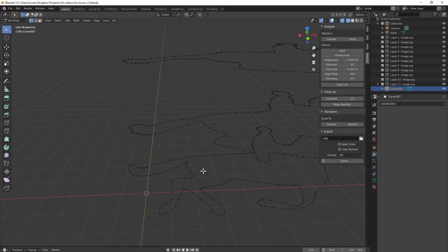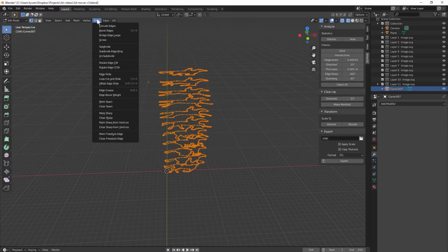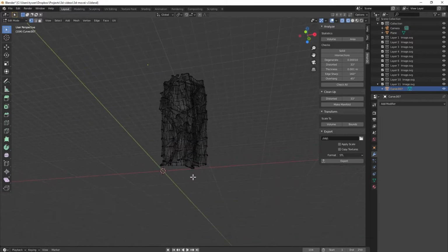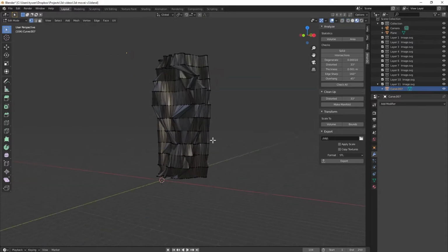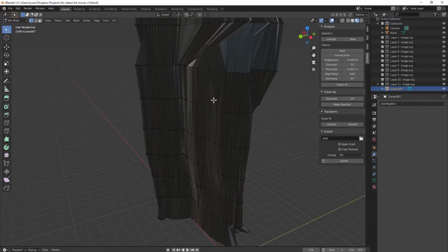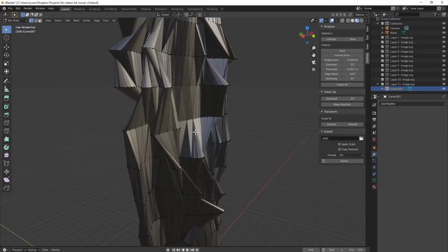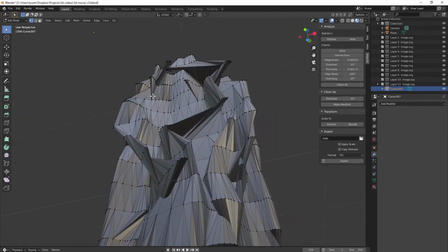It's likely because there's some hanging loop, or this layer is not a continuous loop. And here I see that there's this hanging vertex. If I select it, click X, delete the vertex, do it over again, you'll see that basically fixed it. I'm going to switch over to this face view and you'll see this is pretty much our shape and it looks relatively good. There's some issues here, but for the most part, this is, I think, as close as we're going to get.